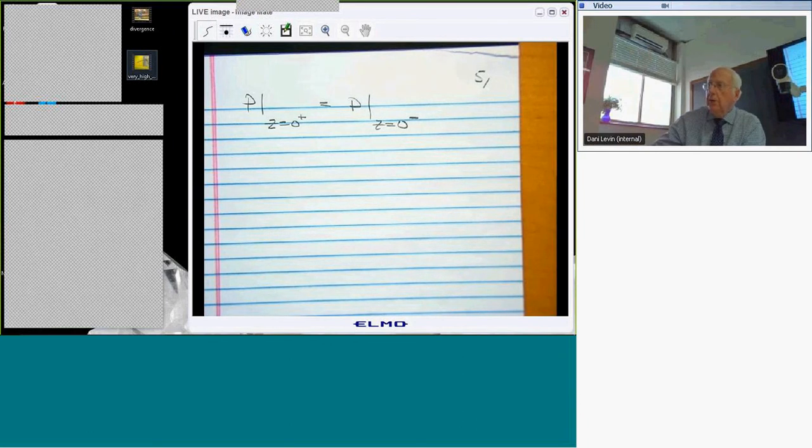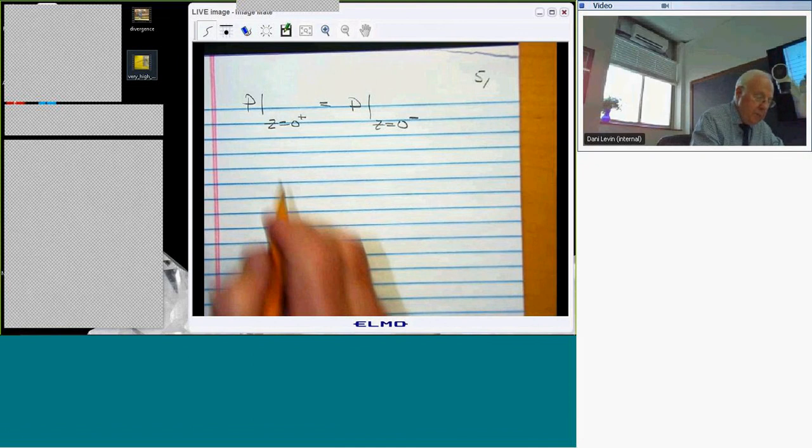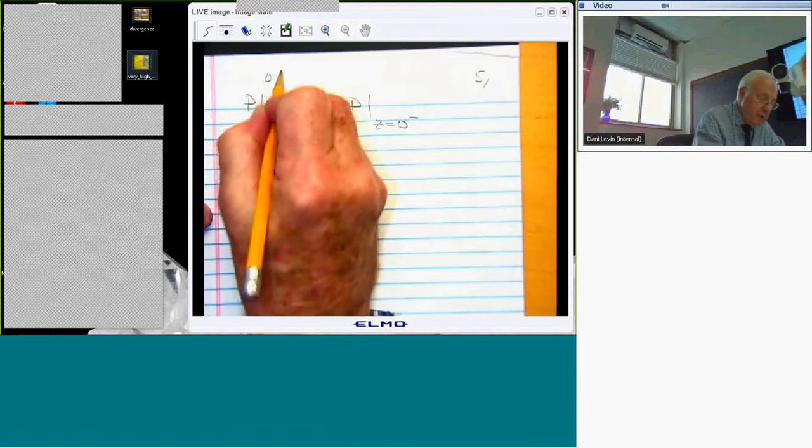By the way, as we'll see in a moment, often the pressure is discontinuous from the top to the bottom of the wing. All right. In fact, if the pressure were not discontinuous, there wouldn't be net pressure and there wouldn't be force on the wing, right? Which would be, well, the Wright brothers would still be trying to figure out how to fly if that were true. So that's not true. But off the wing, I should probably say this is off the wing.